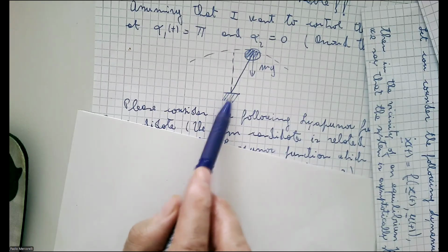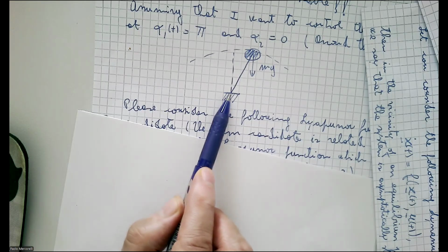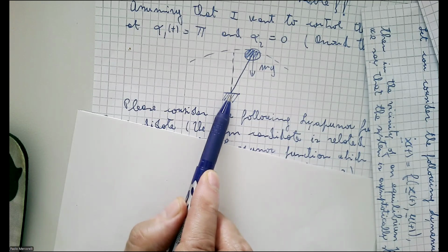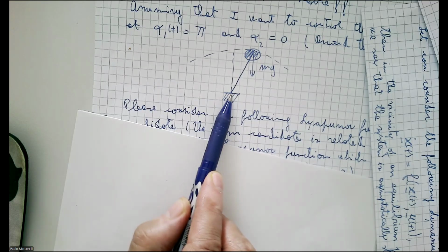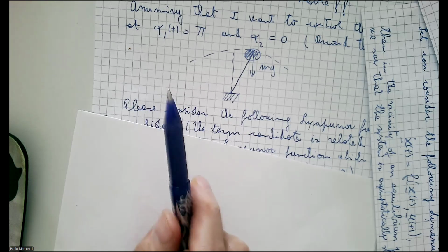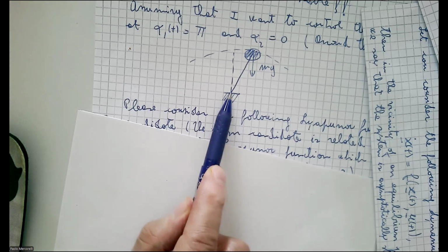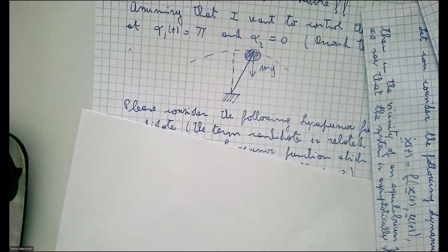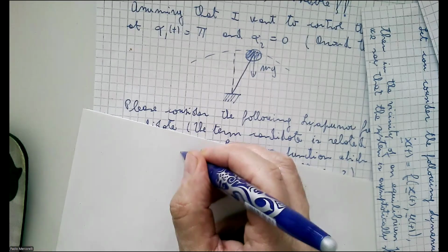Again, the friction here could also be relevant, not only 0. Because this joint here is characterized by the motor. This point here is connected with the rotor of the motor. This friction could really need to be analyzed. In particular, we have nevertheless static friction. Think about the rest moment of a motor. Look in YouTube, no?